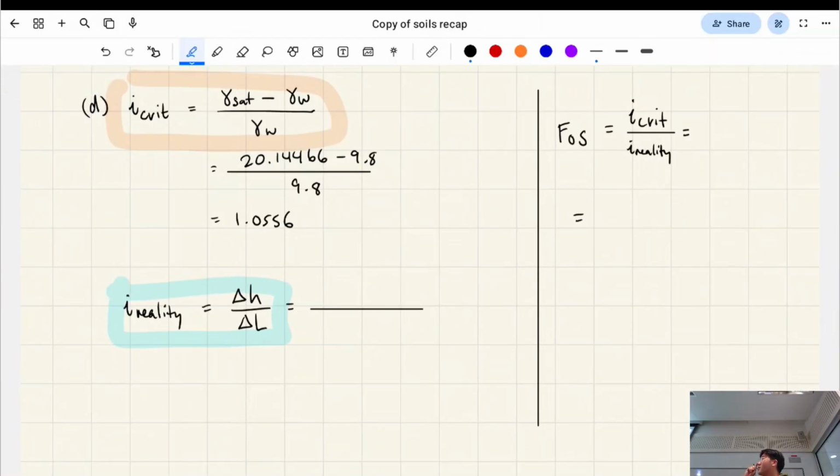And basically for the hydraulic gradient in reality, this is where we focus on that last square, where the quicksand effect will occur first. So that's where we measured 0.8 centimeters, just a second ago. Convert it by our scale.